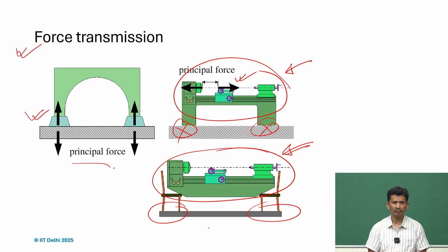So it is very important to understand the load path and what the strategy is. We definitely want to minimize or shorten the load path, and along the load path we may have to stiffen it. We want higher stiffness because of higher dynamics or higher precision. So, for instance, in this case the tool post and tooling, whatever is supported, has to be stiff, not the support.